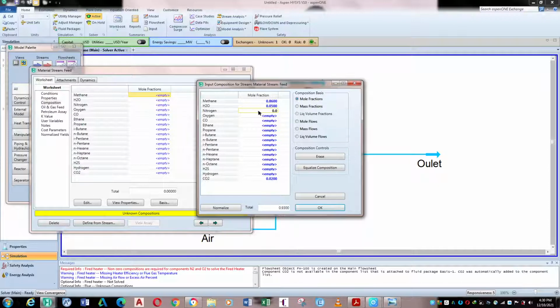So we immediately go on to specify the outlet stream. Vapor fraction is 1, gaseous stream, and then we want the temperature to be 1000 degrees Celsius, and then the pressure, we assume a slight pressure drop, because really we can't have no pressure drop exiting the fire heater.